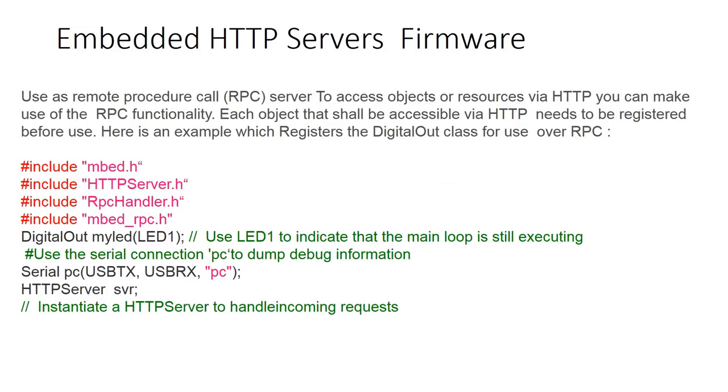Now, how to design firmware in Ethernet? The entire practical example which I am going to give is to measure temperature, to create a temperature server which will give you the temperature at 192.168.1.133/RPC/ give me the temperature. Such a kind of command you are creating in firmware. You are using the ARM MBED microcontroller.